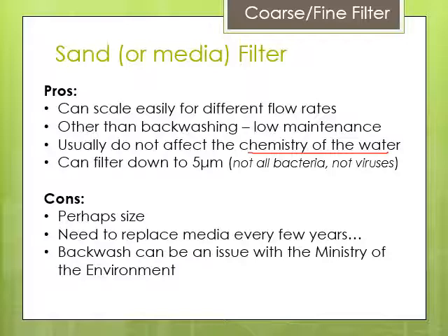As far as pros, the sand filter is very effective all the way down to 5 microns, depending on the media you use. Sand is not usually all the way down to 5 microns. Sand can go down to 10 or 20. But 5 microns, on the next slide I have a picture to show you, but diatomaceous earth works really well, and that will filter out bacteria, but nothing will filter viruses out. They're just too small. We make it through.